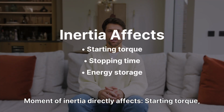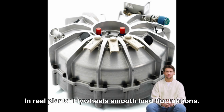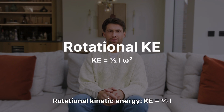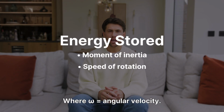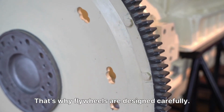Moment of inertia directly affects starting torque, stopping time, energy storage, vibration resistance, stability of rotating systems. In real plants, flywheels smooth load fluctuations. Shafts resist torsion. Rotors control speed stability. Cranes prevent sudden jerks. This is not theory only. This is industrial reality. Rotational kinetic energy, KE equals 1/2 I omega squared, where omega equals angular velocity. So energy stored depends on moment of inertia and speed of rotation. That's why flywheels are designed carefully.